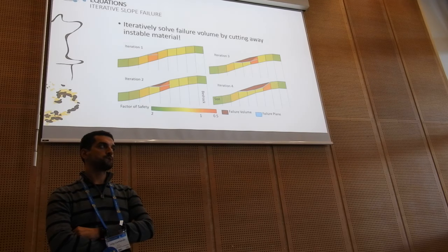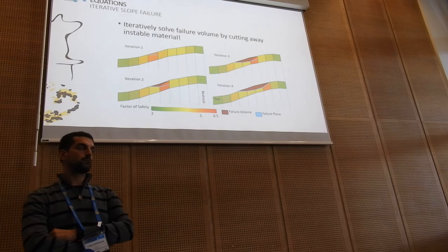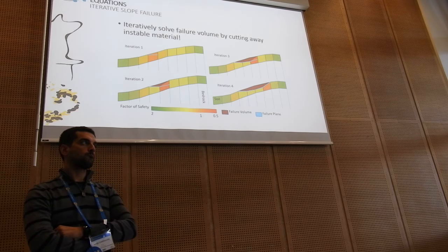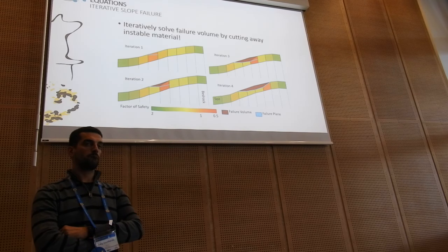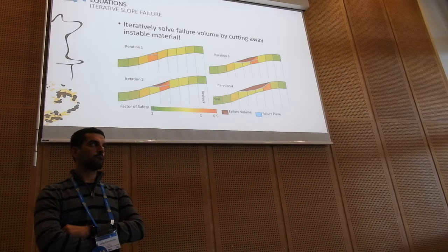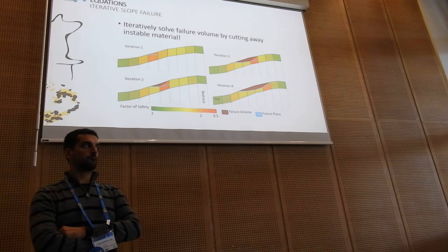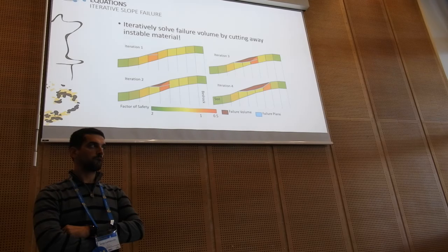Well, in principle, we assume that in our soil, every potential plane that you can envision between the top and the bedrock is a potential failure plane, and the friction that we use at those planes is always the same. So we do not treat the bedrock interface as a very special case in that sense. Which is maybe something we should include. So if you have ideas about how to.